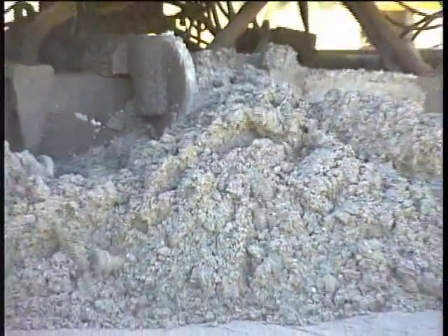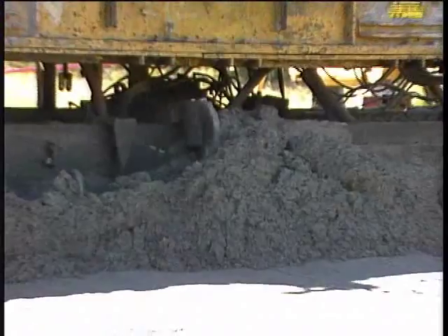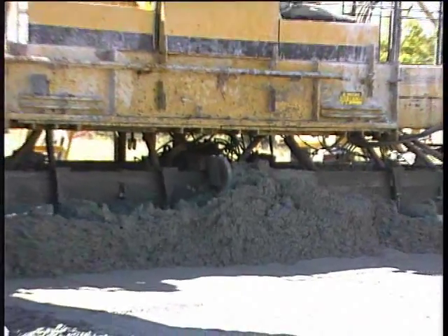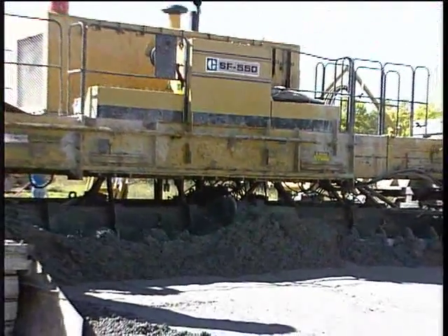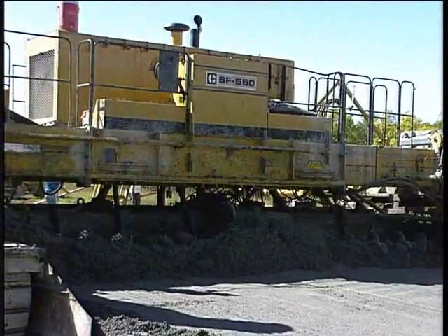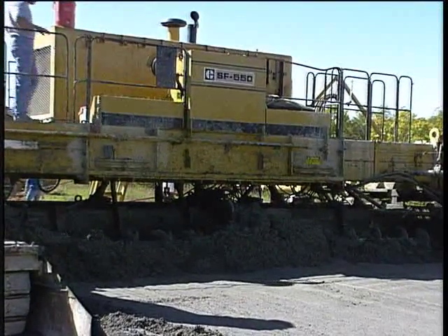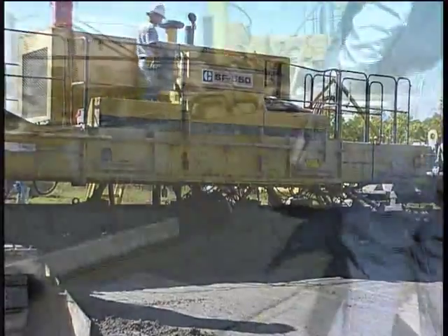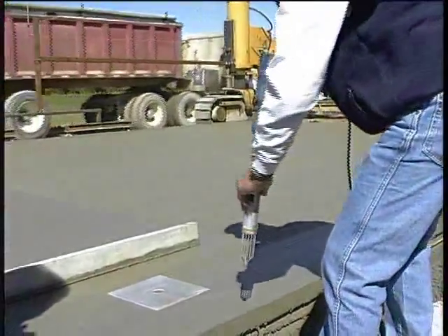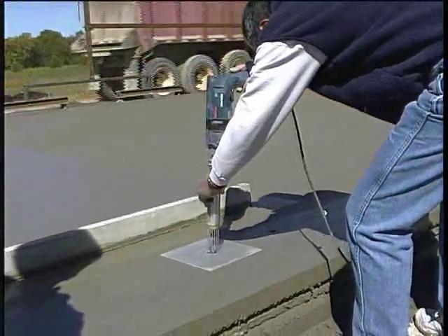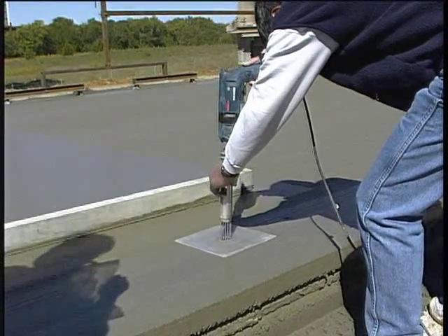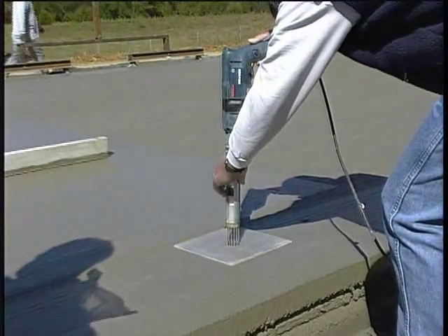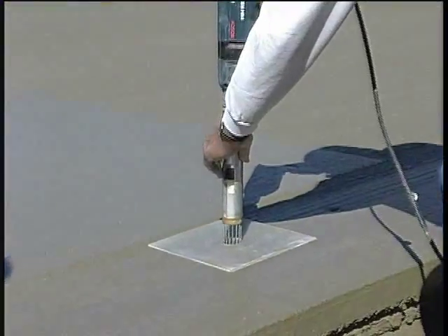The air void analyzer, known by the acronym AVA, analyzes fresh concrete produced on the project. Typically, the sample is taken behind the paver after all the heavy vibration and manipulation have been applied to the concrete. This gives the actual spacing factor of the pavement concrete. Samples are taken from both the path of a vibrator and the gap area between the vibrators.